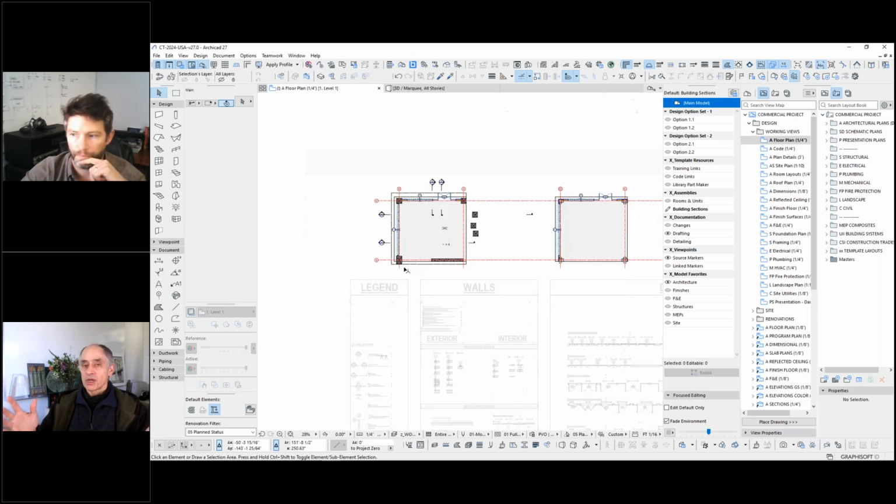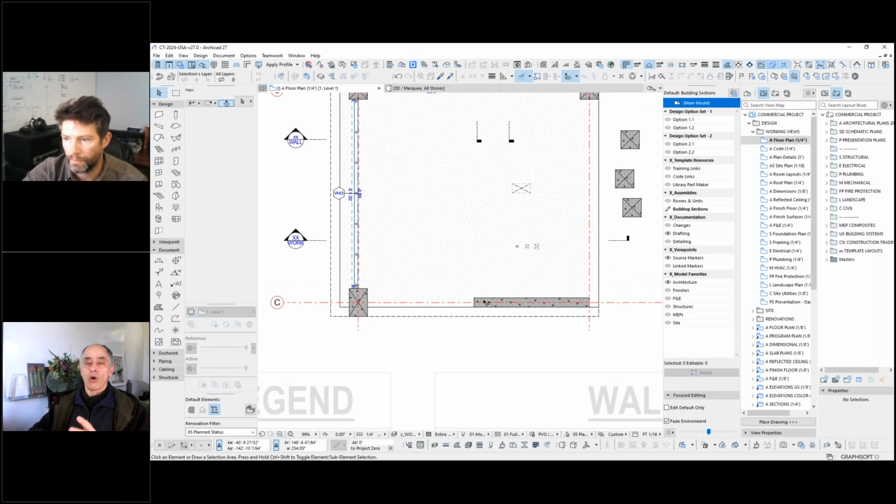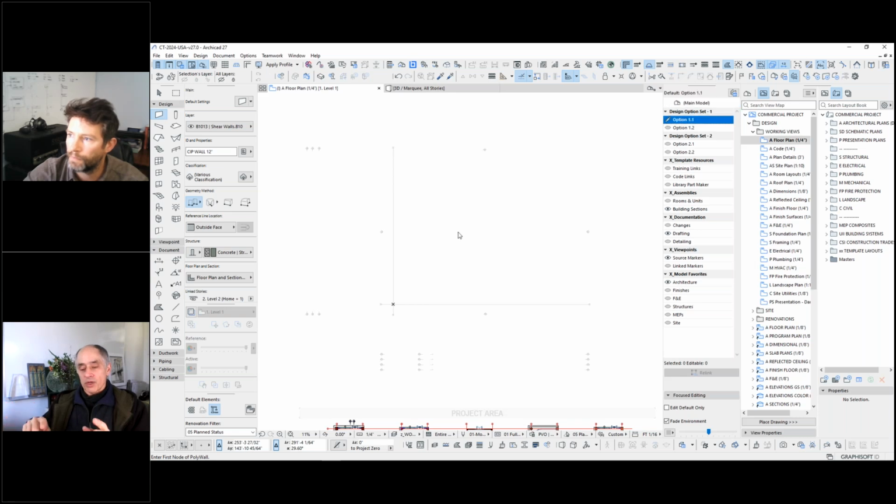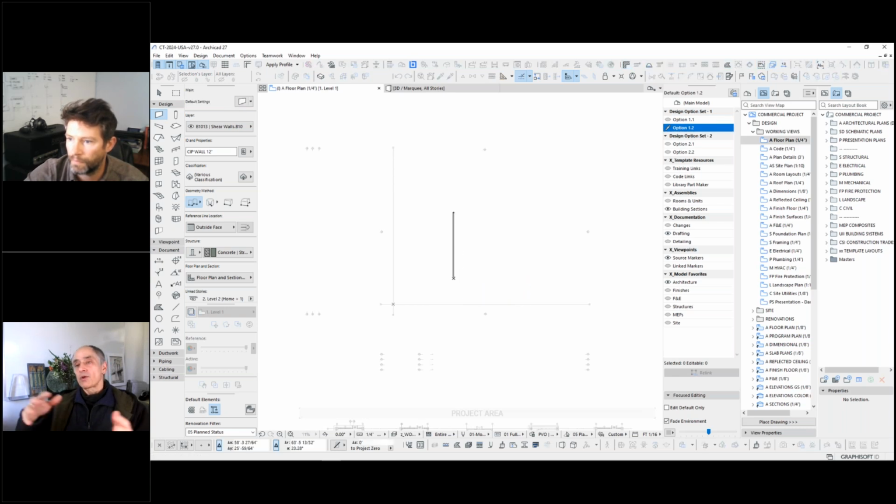Okay, so what is a design option for in Graphisoft's primary use? It's to say we have 3 versions of the kitchen. We want to have different arrangements of the cabinets and interior walls or whatever, and the rest of the building may be constant, but we're going to say, let's look at option A or B or C, and when you click these design options, different groups of elements will show, and every element that's in a design option only shows on one, but there is the concept of other parts of the building, particularly the main model, that always is showing.